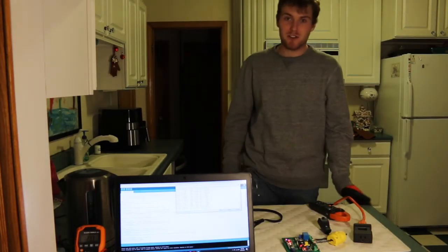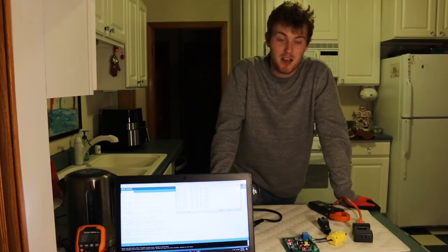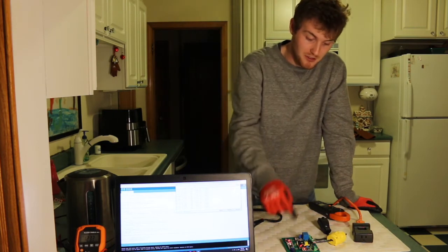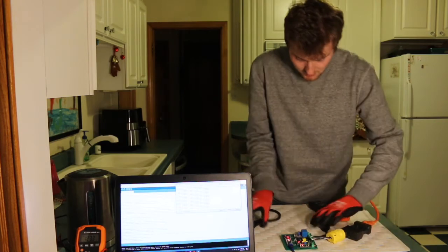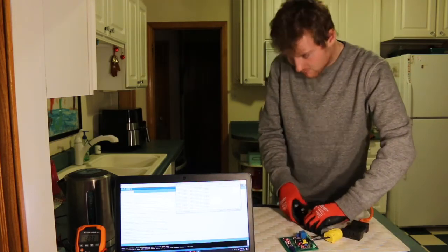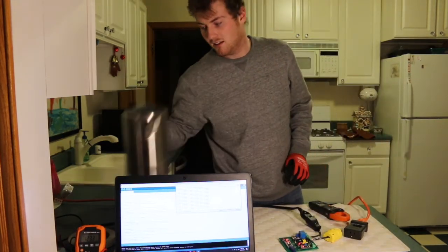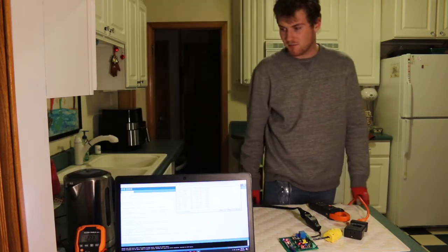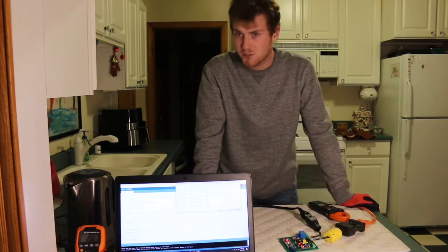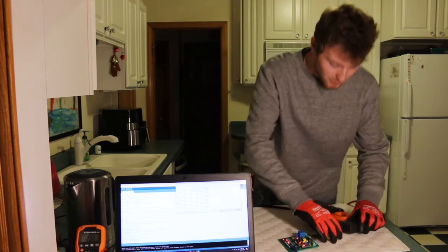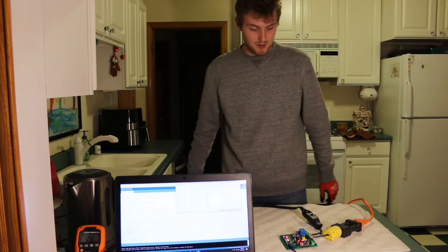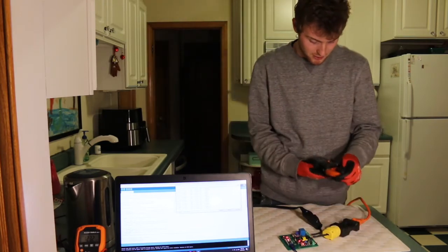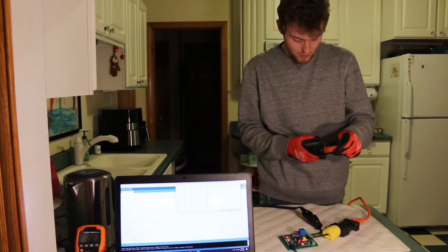All right, so we're going to be looking at the Smart Home IoT power meter, which will deliver power metrics from sensors on the board. So right now, I'm going to plug in the load first, which is a tea kettle. We should be expecting something in the range of 12 amps or so, and now we will plug in the mains voltage to power on the board. We'll check the current reading with a clamp meter.